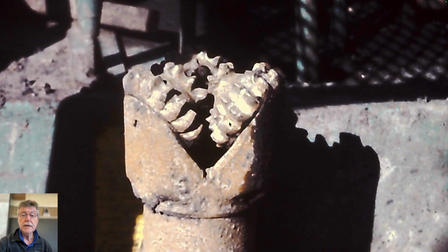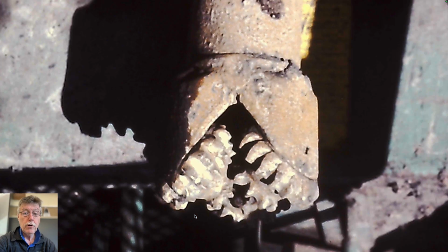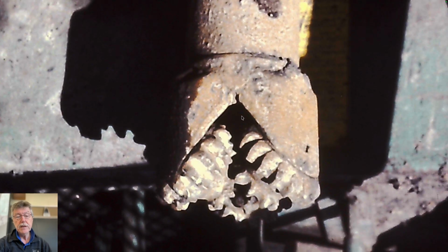Tricone bit, just as we said. Three cones on a spindle. It doesn't cut and it's not driven. It just is rotated by the rotation of the drill steel on the bottom of the hole. As a result, these runners just run over the bottom of the hole, and there's enough force on each of these little teeth that they break off portions of the hole. And then the water, it's upside down, of course. The water comes down, the drill fluid comes down the drill pipe, out of the bit, washes away the cuttings, and then returns it back on the other side. Good.